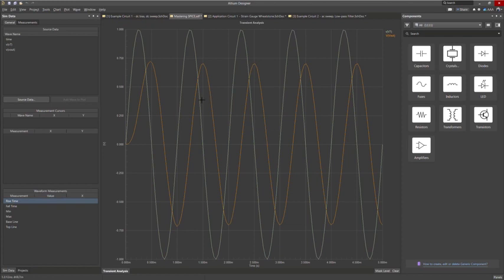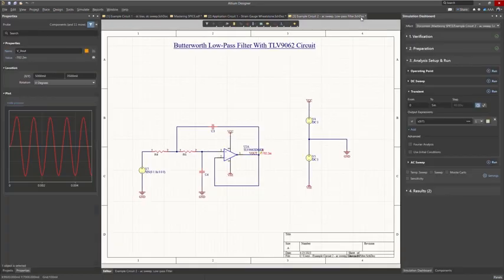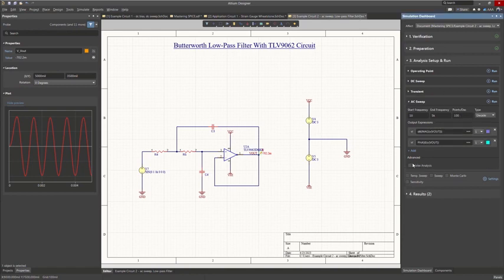And this is kind of interesting. So we do have some attenuation here and also some shift going on. So let's further look at our circuit. To look at the overall performance, we're actually now going to do an AC sweep. We'll start from 10 hertz to 5K, and we'll do 100 points per decade. Again, you could always add more points or less depending on the resolution you want, and time to analyze. Higher resolution, I think, is always better.